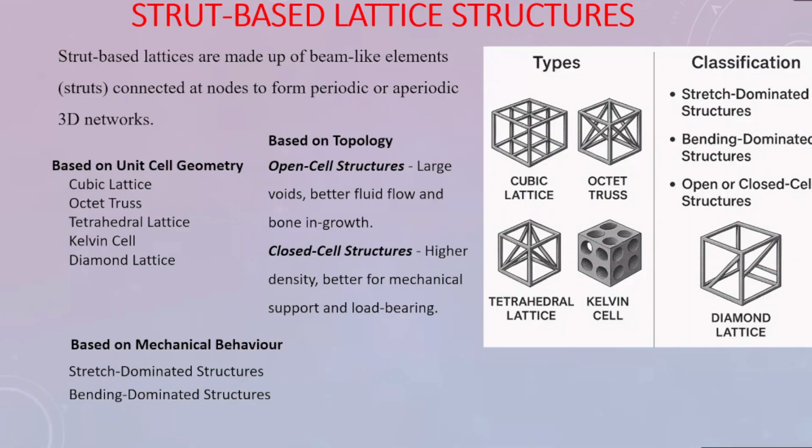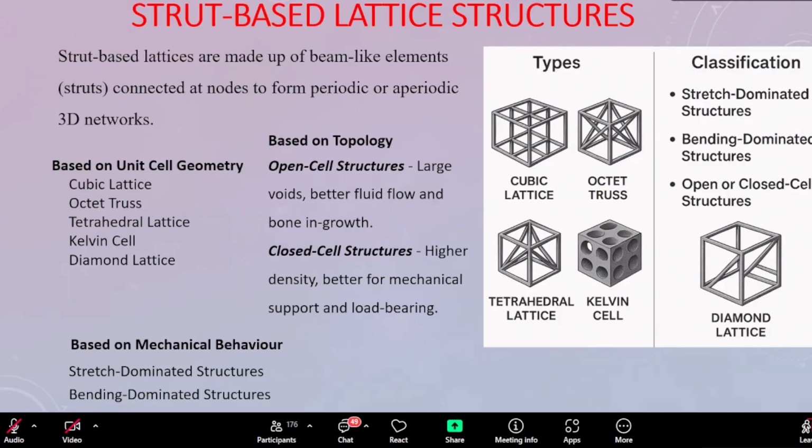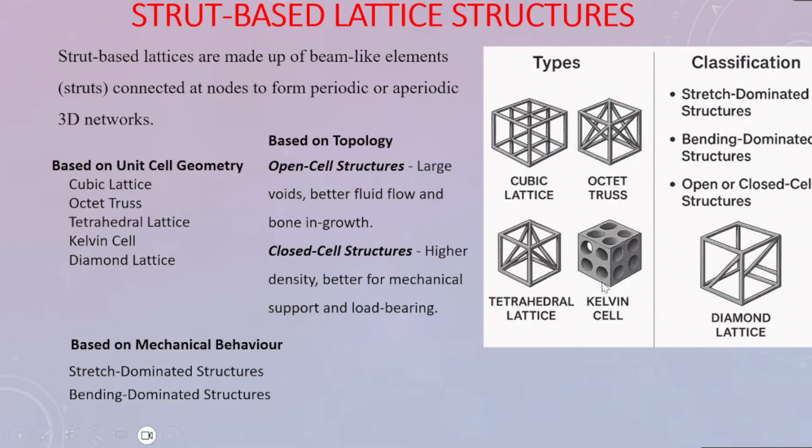Then you can have your own unit cell with your own lattice structures, which gives you novelty in creating lattice structures. You can do applications like thermal or load carrying applications, and you can compare with the standard ones. People have tried only the Kelvin cell or similar cells, which they found much more effective compared to the BCC lattice structures.